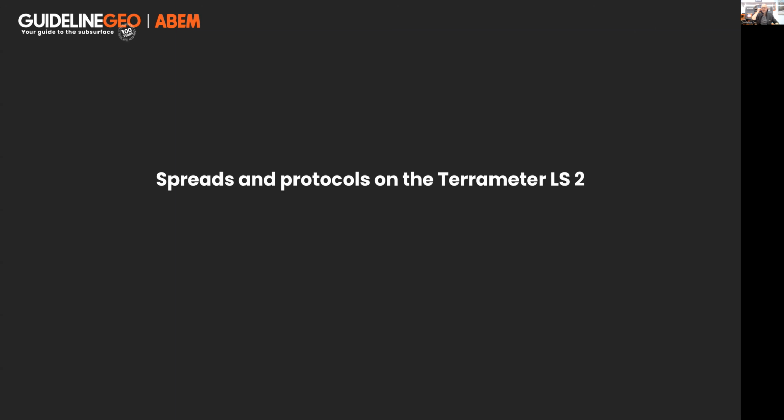If you're doing a 2D survey, most people are quite happy to just take the preloaded measurement scripts on the instruments and run them as, you know, a good robust method of collecting the data. But when we move into the 3D realm, what often happens is people say, well, I don't actually want a square layout, because maybe I want to stretch it into a rectangle, so I get a bit more depth in one direction, and then I just get a slightly shallower sample across in the other direction.